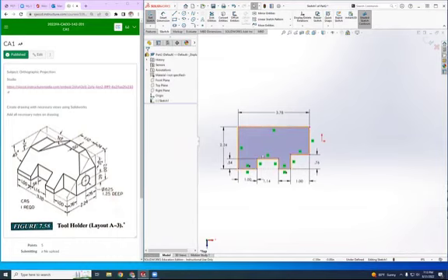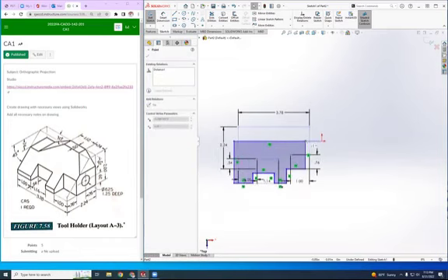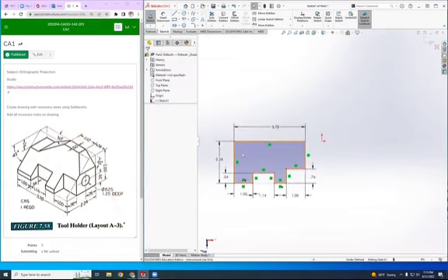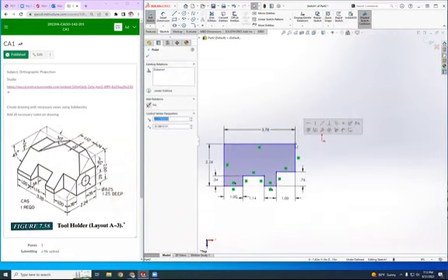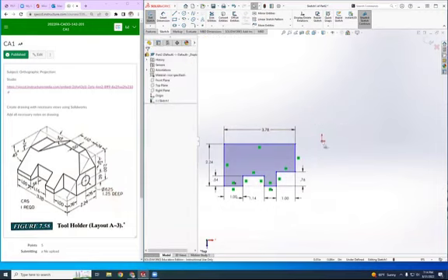So when you're sketching, if you would have aligned it, it would have given you a collinear constraint, and that would have given you lots of errors. Now, I want to do the same thing again, try to skew it. Now notice that this sketch is still blue. It's not fully constrained, meaning it can be moved along the space. It can be skewed, possibly. So we need to pin it to the origin.